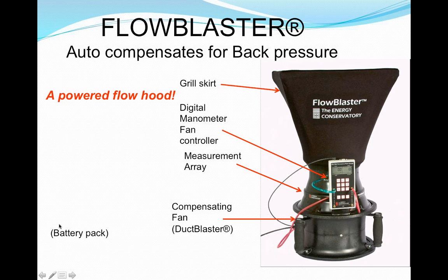You need a battery pack to wear on your belt when you run this to power the duct blaster, and it does provide very precise measurements. I've heard within plus or minus 10 CFM or even closer than that to actual measurement. It does test out well.